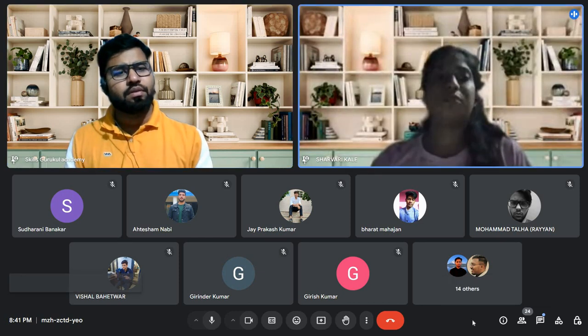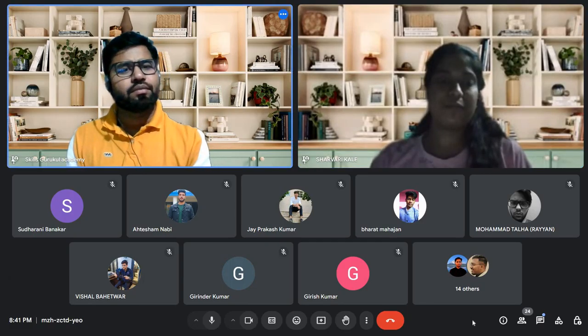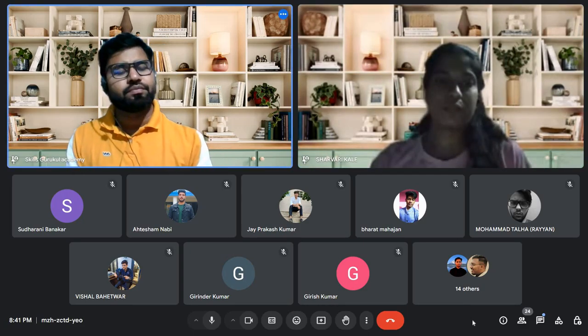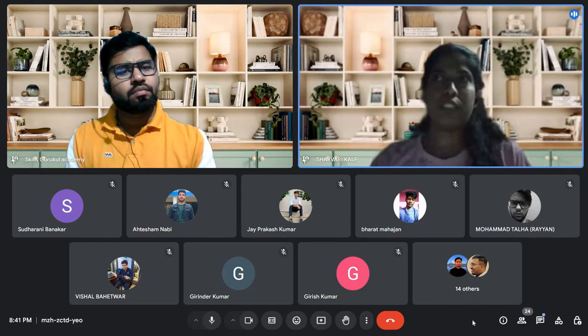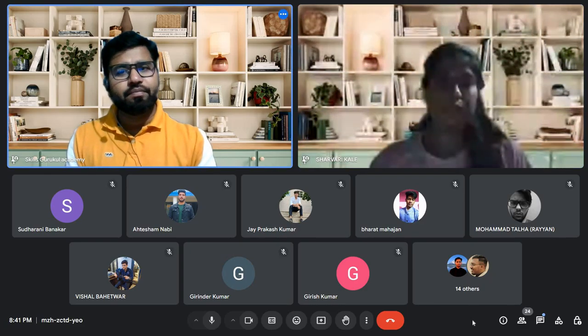And detail oriented. Okay. How much cover do we provide in a column? 40 mm. Okay. And for a beam? Beam, 25 mm. What is the difference between a one-way slab and a two-way slab?